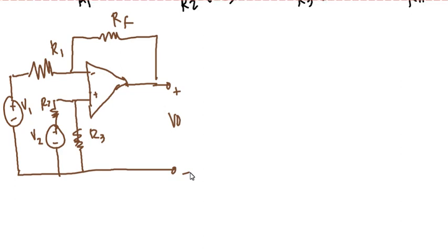So what is the concept of the differential amplifier, or difference amplifier? It amplifies only the difference between the two inputs. Then it neglects the signal that is common to both inputs. So that's for your difference amplifier. Still the same concept for calculation will be superposition and the concepts we discussed.